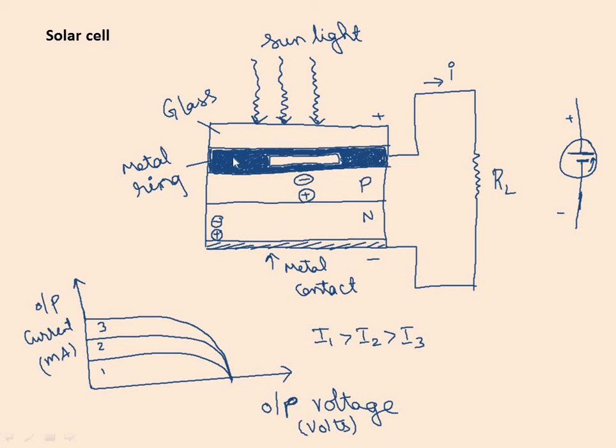When light falls on this, and of course you can see the glass protection over this, the temperature increases at the junction, and thus there is movement of the charge carriers, and we can get the output. Suppose we speak in detail about the working here also, it will be better for our understanding. When light photons with energy reach the junction, they excite electrons from the valence band to the conduction band. When the electrons leave the valence band and enter the conduction band, they leave behind holes. That's obvious, isn't it?